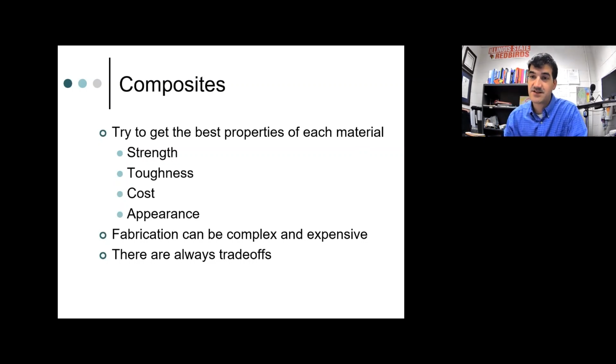The way you do that is you lay down the fiberglass cloth. It's like fibers, like a mat. And then you apply the polyester polymer or the epoxy, whatever base polymer you're going to have, and you spread that over it, and then you let it cure. But that's a fairly time-consuming and relatively costly process. Then sometimes you vacuum bag it to get the excess polymer resin out of it, because that's just extra weight. So all of that tends to be fairly time-consuming and kind of expensive for fabrication.